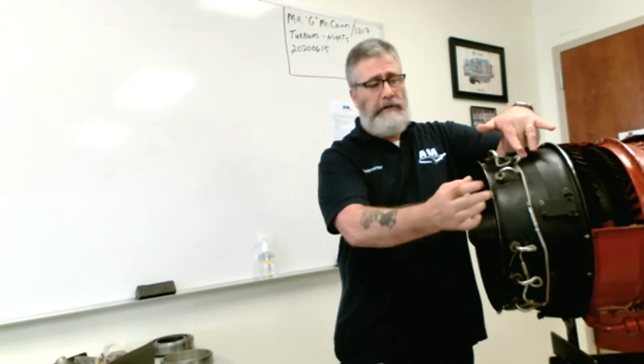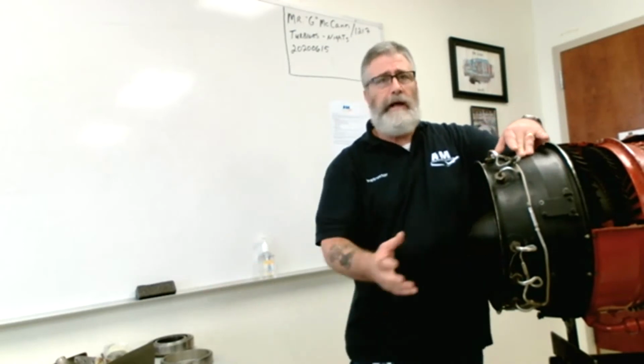We're going to talk real quick before I disconnect about afterburners, all right? So afterburners, the way they work on military aircraft, is they take the air that has already been burned, which still has air molecules in that exhaust, they pump in additional fuel, they relight it with another set of igniters, and then we get that sudden burst of speed that we've all seen in Top Gun and all these military movies, right? This is a great design. It's been around a long time.